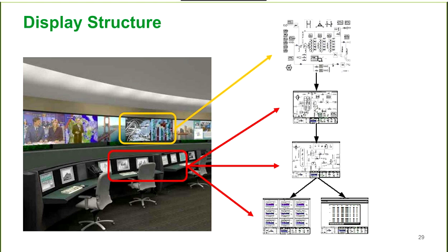This one displays just an example of what it could look like. You put your overview, level 1, on the big screens. Then down on the operator desk, the operator has the possibility to go in on level 2, where he is actually starting and stopping pumps and equipment. And then he can also go down to the P&IDs and do the forcing of the values.